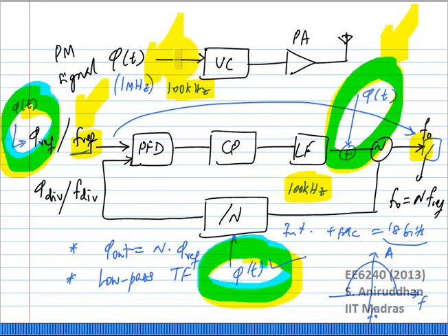As we moved on, we actually wanted to transmit more and more data, and the more data you want to transmit, the bandwidth of the signal keeps increasing. And today we are talking about 4G systems or wireless LAN systems, where at a minimum you are transmitting data at 20 megahertz. Right? The bandwidth of the signal is 20 megahertz. We are talking about wider bandwidths also, but let us take the example of a 20 megahertz signal. Okay?